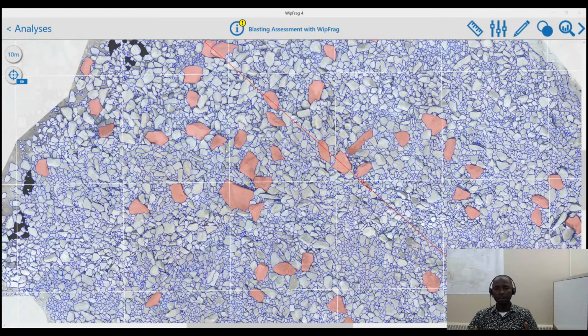The second function of the tool is that it has the ability to assess the whole of the blasting and judge the size of the fragments as a function of your crusher or your loader. So how do you do that? You need to click the tool a second time. When you long press the tool in this second mode, you can put in the size of your crusher. Let's assume your crusher is a 1300 millimeter gape, excuse me.